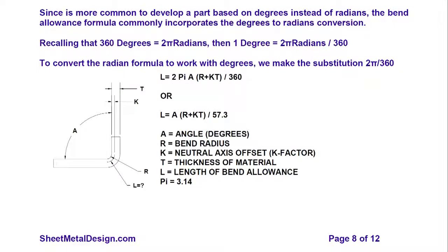So, what is done normally is, depending on the practice in the workshop, you usually have a table. In the case of what I have shown you, for all our 1.6 and 1.5 mm aluminum materials, an allowance of 0.65 millimeters is added to the internal dimensions. So, you have a simple L, I have limb A, I have limb B. Suppose this is 40 mm and this is 40 mm, I take the two internal dimensions straight away. Mind you, I am not talking about the clamping position, I am just talking about the flat length. When it is laid out, how much flat it will come. So, this is what I tried to show you that day.